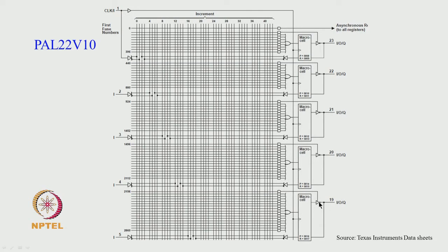Then it's possible to implement. Or you take a tree approach: 4 2-input XOR gates which will consume all the 8 inputs, giving 4 outputs that can be combined in the next 2 XOR gates.